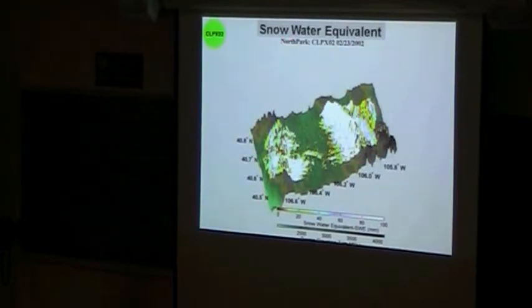And what we did is we flew the aircraft again back and forth, and we took the observations, which in this case were at 18 and 37 gigahertz, different frequency for a different environmental variable. And we developed an algorithm based upon NASA's use of satellite data that gives us the snow water equivalent. And then we georegistered it. And you can see very clearly that in the valley over here, where it's typically a little bit warmer, you don't have as much snow. On the other hand, over the mountain peaks, you have a lot. This was able to be done with a spatial resolution of about 100 meters.